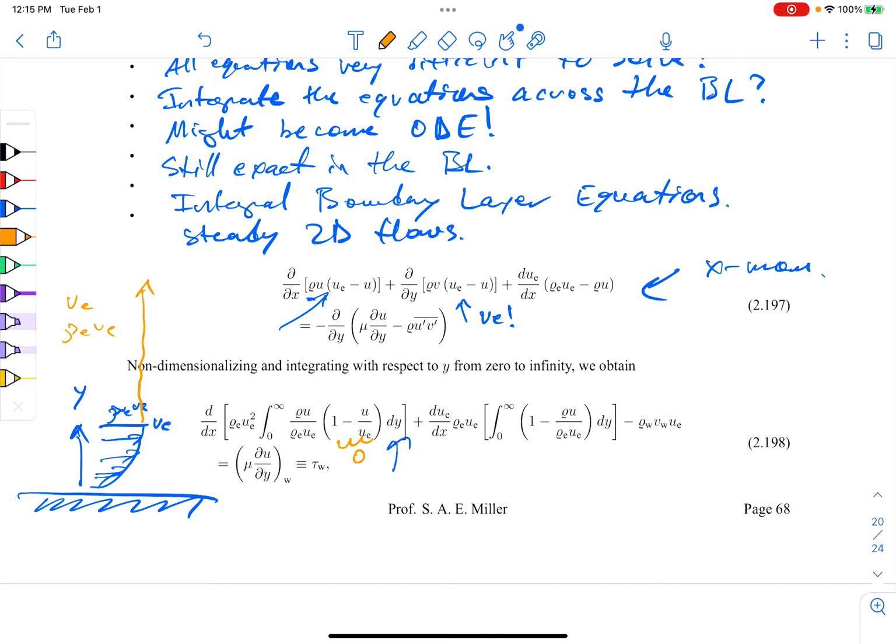If I wanted a particular property of the boundary layer, instead of writing infinity here, I could have set it to, say, some value of y, for instance, right? And then I would have this integration done from the wall to some point y. But I'm letting it go to infinity, which is fine, because all these terms in these equations are going to 0 as the integration goes to infinity.